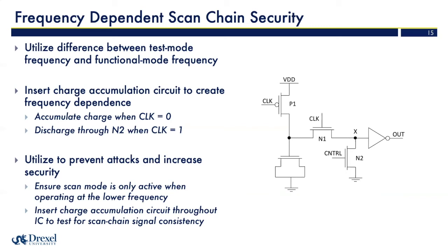And we can then also have a locality-based security where if someone's trying to insert a fault at a given location, these other charge accumulation circuits throughout the design will give a false reading and not allow scan mode to be entered.